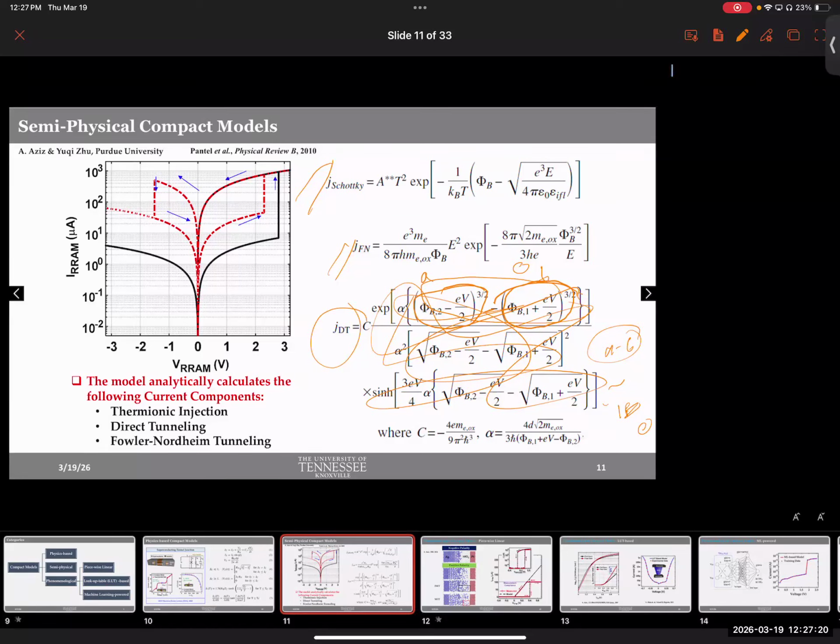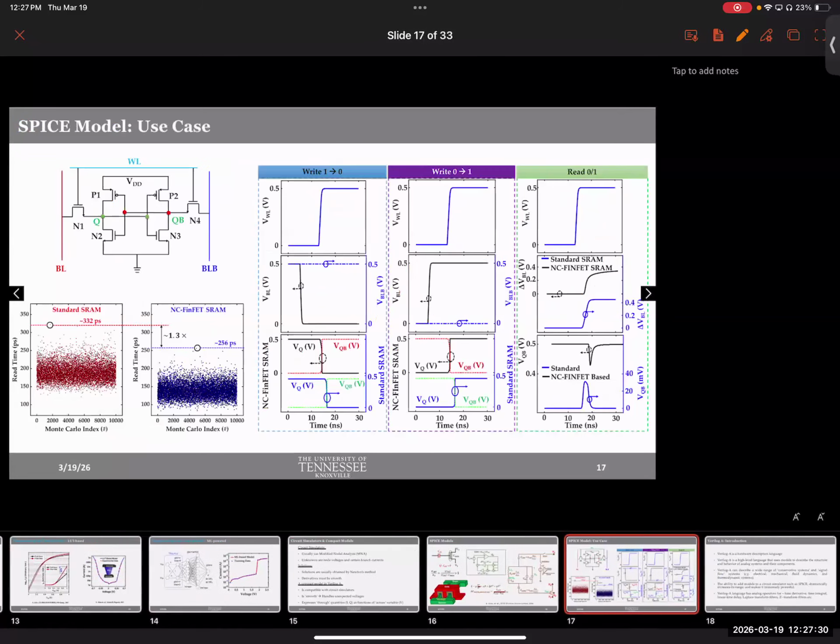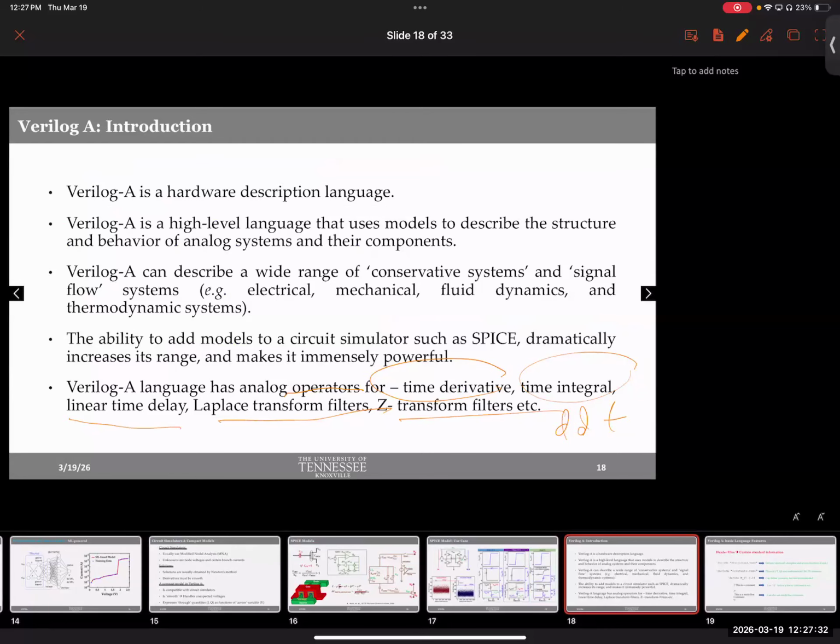So that's how you debug. Your current is 0. Oh, why is it 0? I've incorporated everything. Okay, that's what's going on. So now it's a super boring slide that shows you, okay, 1 ampere minus 1 pico can be a problem. But if you have it in mind, then you know, oh, precision could be an issue. Let's calculate individually using MATLAB or something and see how the numbers look. And when you see something that has lower precision, you can scale it up temporarily, meaning you can use a factor. You can multiply it by 10 raised to 12 and make it artificially big so that it is not ignored.